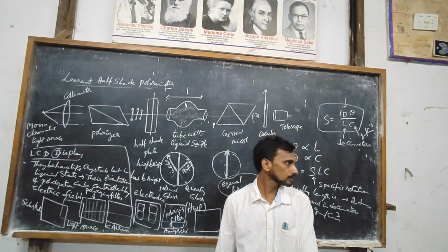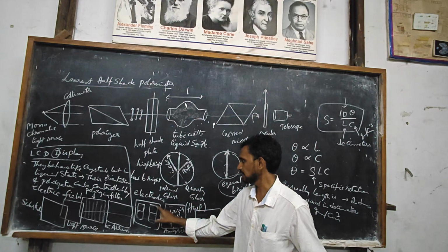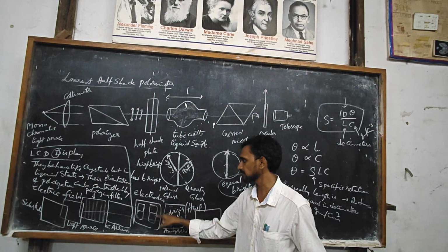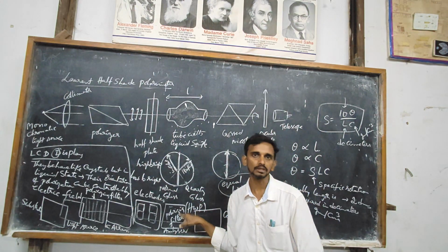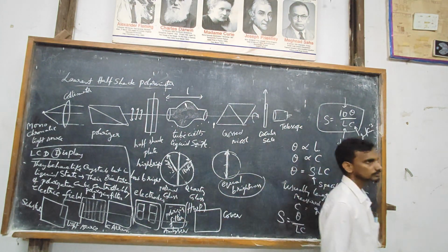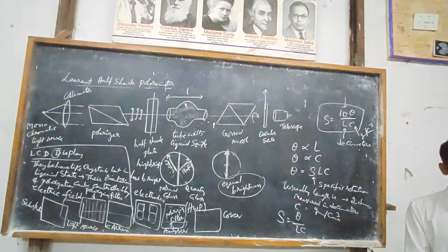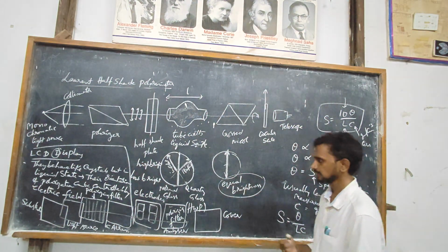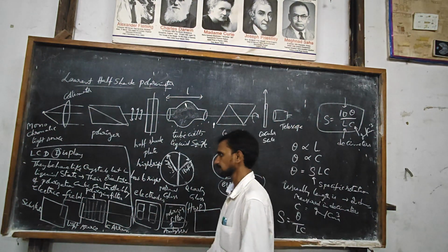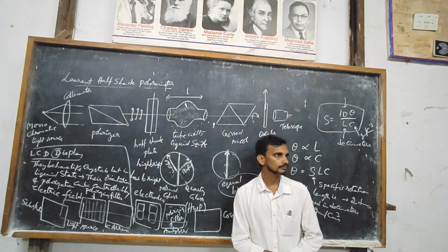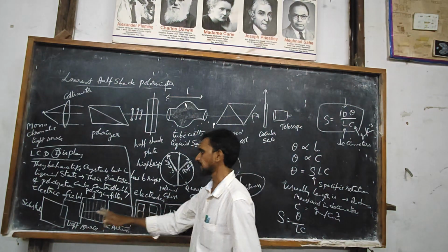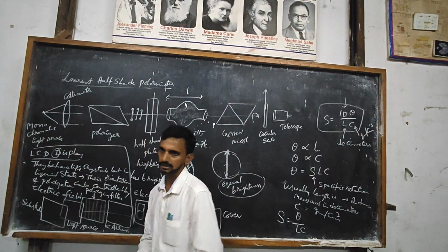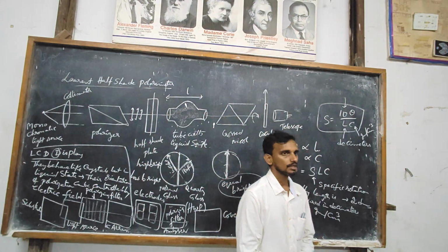So when you apply an electric field, wherever the electric field is applied, the crystal orientation changes and output intensity becomes 0. So we see dark bands wherever that electric field is applied. Right? So that is a backlit type LCD, liquid crystal display.